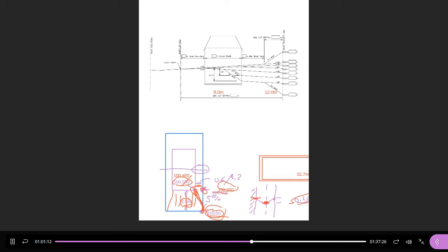Suppose you want to have all usable backyard space. So if you start with an elevation of 0 at the front, go all the way to the back of the lot as steep as possible. So in this case, 3%. Remember 105. What would the elevation at the back be if I want all usable backyard? Yeah, that's exactly what I get.